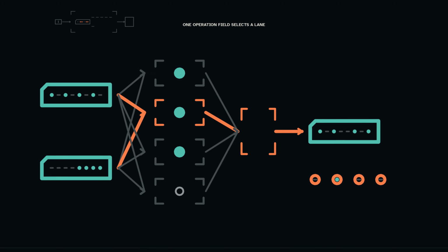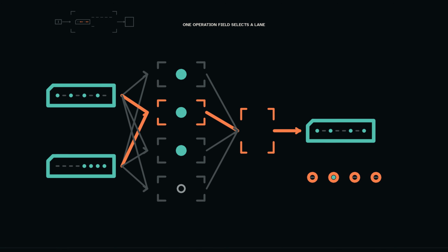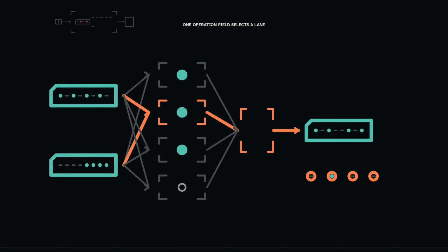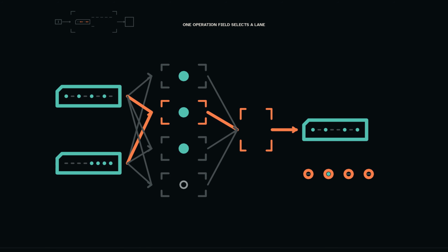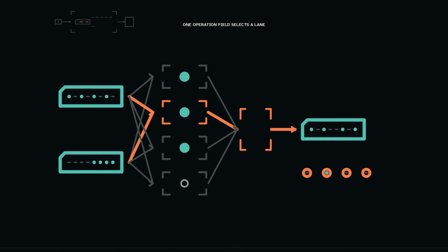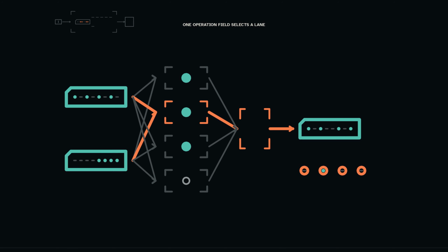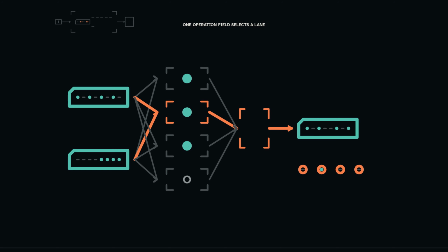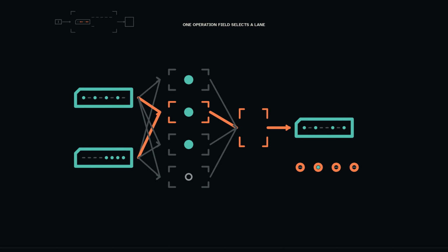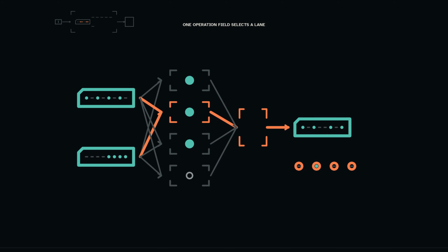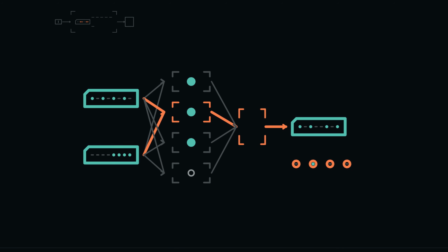Now predict an unfamiliar ALU state. Operand A is hexadecimal AA. Operand B is hexadecimal 0F. The operation field selects exclusive or, and the selected result is hexadecimal A5. Zero is clear because the result is not 0. Negative is set because bit 7 is 1. Carry and overflow are cleared by the logical operation contract. If the operation field changed to and with the same operands, the selected result would become hexadecimal 0A with zero and negative both clear. Operands alone do not determine the result. The declared function selection completes the contract.